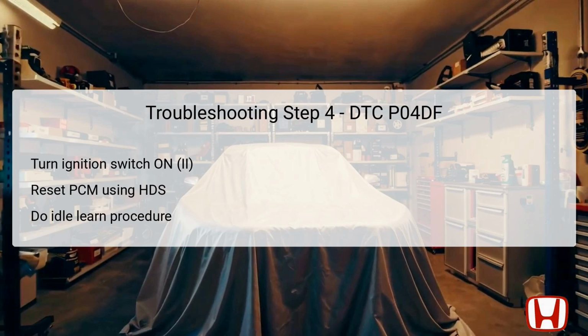Resetting the PCM is essential after significant repairs, as it clears any stored fault codes and recalibrates the engine management strategies. After the reset is performed, executing the PCM idle learn procedure is crucial. This procedure allows the PCM to adapt to the new component and adjust fuel delivery and idle speed accordingly.